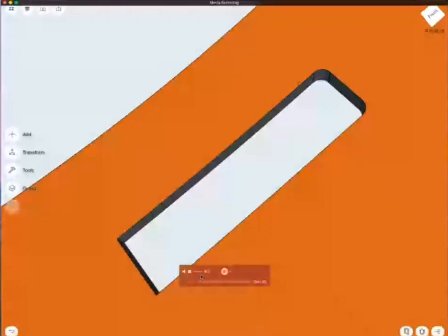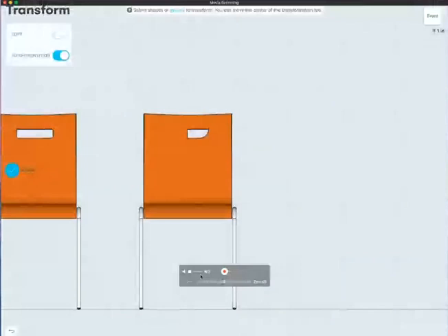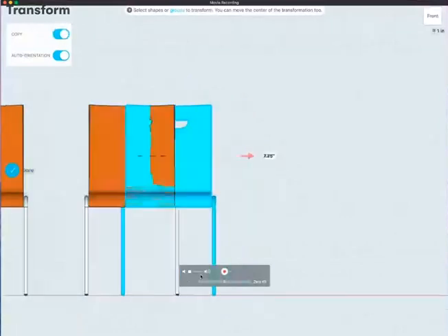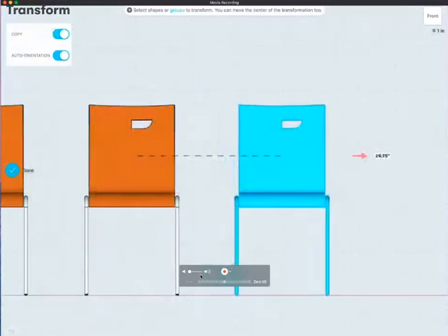So you can see one of the advantages here is because I'm not linked to the sketches and the timeline and the association between sketch and then the features, that I can make copies. And because I can make copies, I can also compare different design ideas very comfortably.